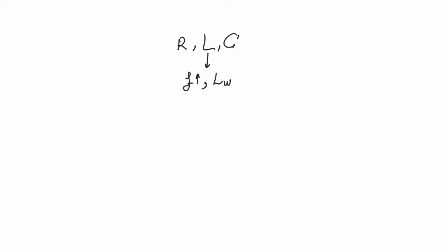So inductance generally increases when the area of the wire is big, which happens when the length of the wire is really long. This is always the case, by the way, for off-chip communication, where you are talking about the copper tracks on a PCB. In that case, you have to take inductance into consideration. But we will see that it's also true for some on-chip wires as well.